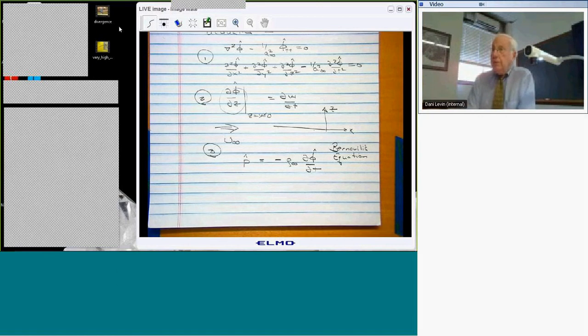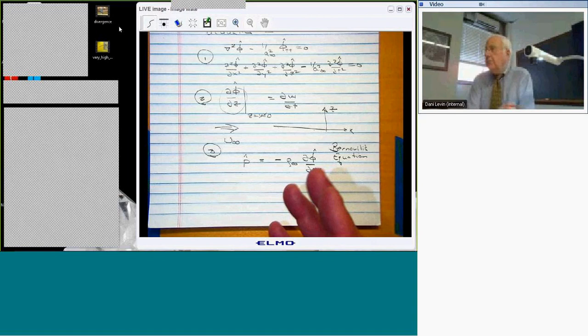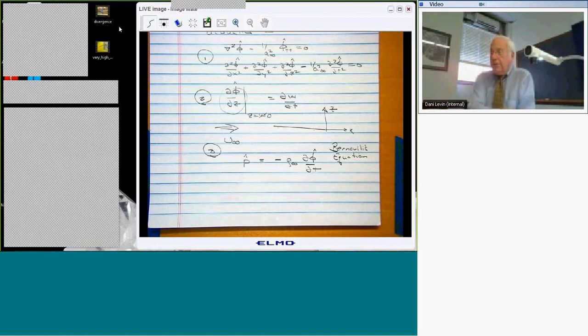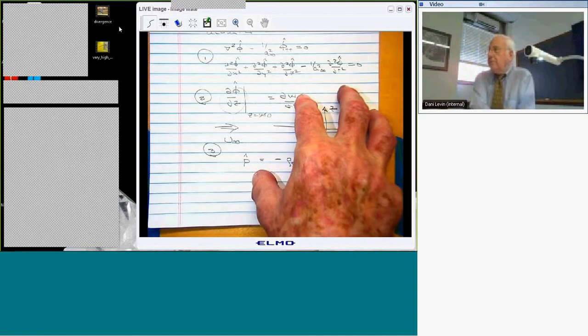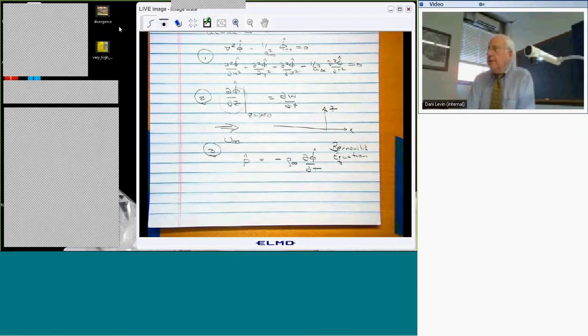because it turns out that when the mean velocity u infinity is greater than the speed of sound, this truly is a wave-like equation. But when it's less than the speed of sound, it becomes more or less like Laplace's equation. And then right near Mach 1, this whole classical theory breaks down, and if you go to the next approximation, you get something that looks a lot like the heat equation. So unsteady aerodynamics has all those classical equations buried in it if you pay attention.